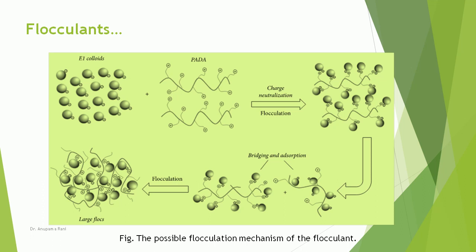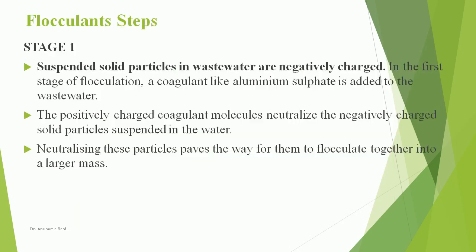Here you can see how neutralization of charge happens when a polymer is added to the colloids. At first, the small flocs are formed, followed by the larger flocs. Let's see different stages of flocculation. Stage 1. Suspended solid particles in wastewater are negatively charged.